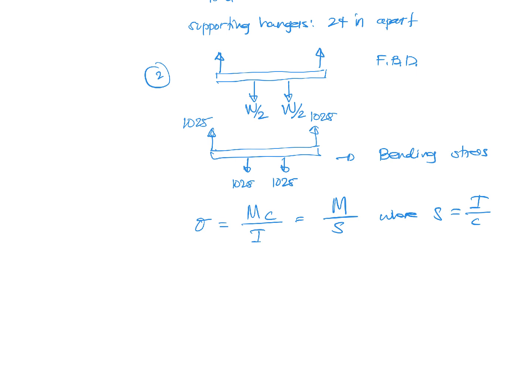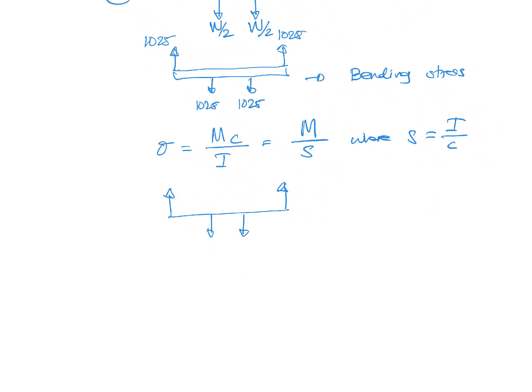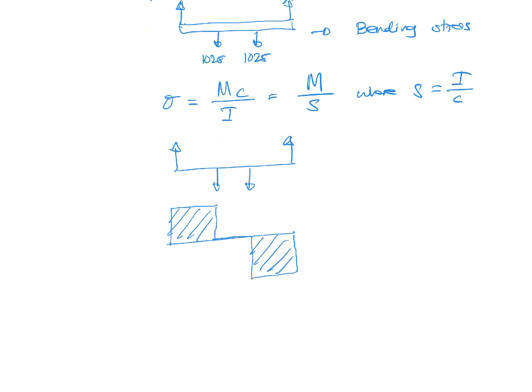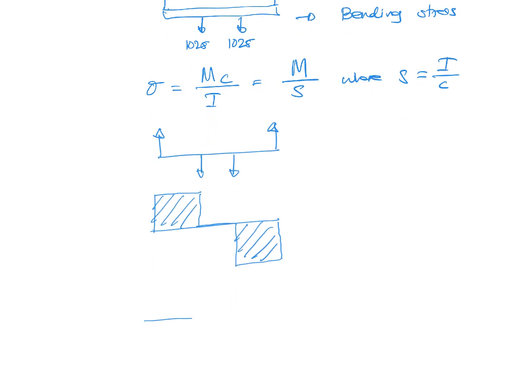So we have the loading diagram here, and from the free body diagram we could draw the shear. Going up, no force, and then there's force going down, and then no force, and then going up. So the shear diagram should close, and that is also similar with the moment diagram.